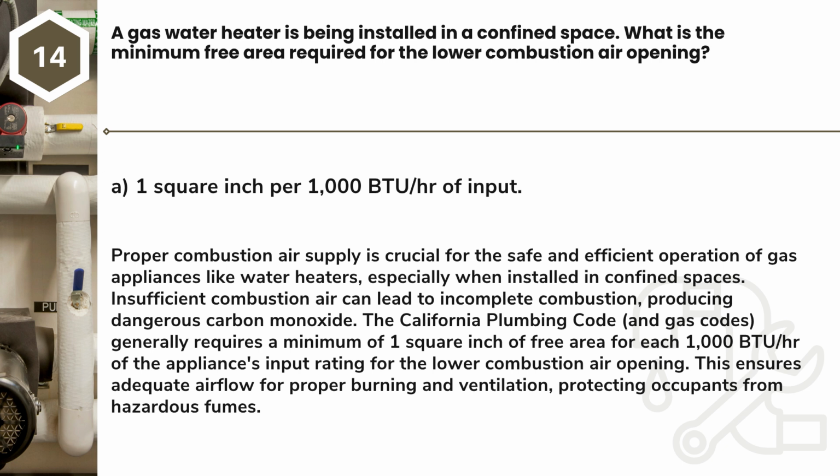Answer: A. 1 square inch per 1000 BTU/HR of input. Proper combustion air supply is crucial for the safe and efficient operation of gas appliances like water heaters, especially when installed in confined spaces. Insufficient combustion air can lead to incomplete combustion, producing dangerous carbon monoxide.